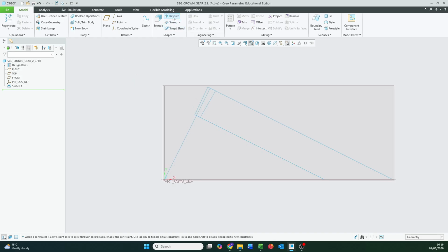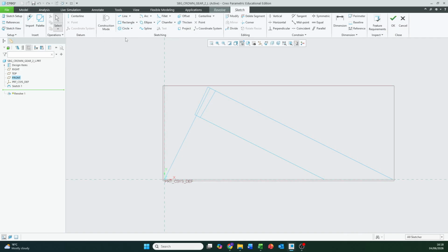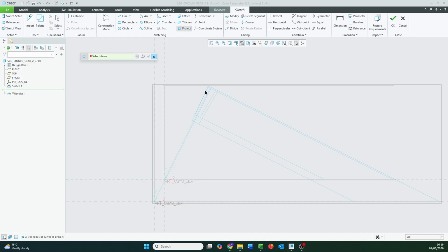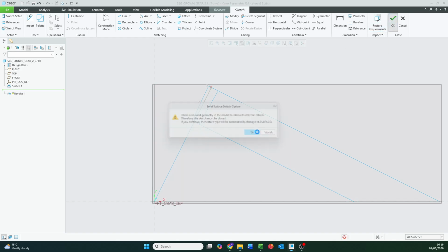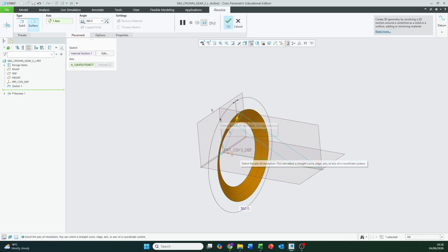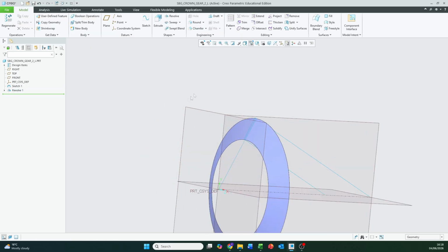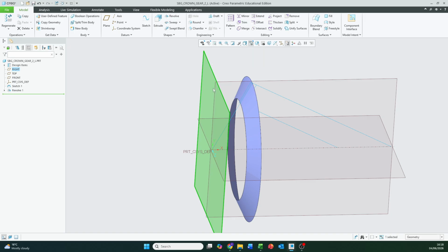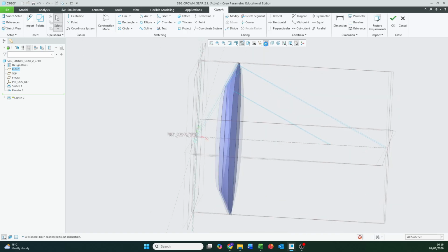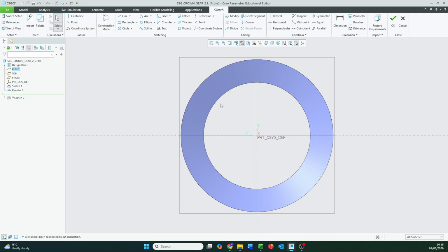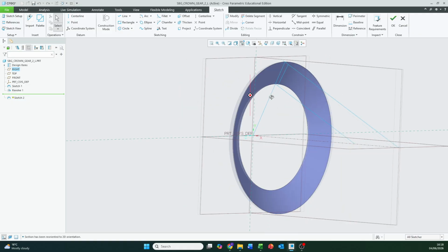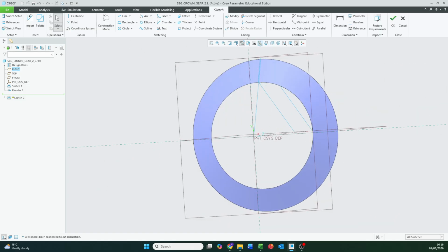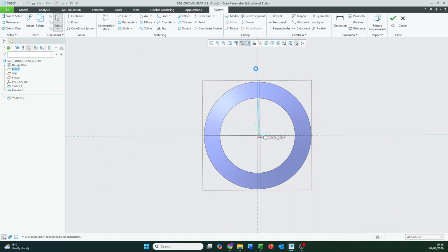So first off, let's revolve our surface that will end up projecting our tooth trajectory line onto. So project, press OK, press OK. Yes, I want it to be a surface, and revolve. OK. Next up, we're going to be sketching on the right sketch orientator view. Now again, I don't want to sketch from an orientation underneath this cone. I want to sketch above, which means I need to reorientate our view to left.